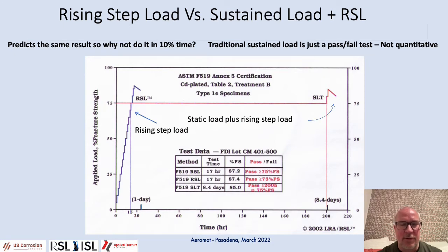So the rising step load method is an analogous method that can be compared with the sustained load method that's been used for a much longer time period. And ultimately, the reason you would select to use them is this. They predict the same result, but the step loading method can provide that same value in a matter of hours or days as opposed to weeks.